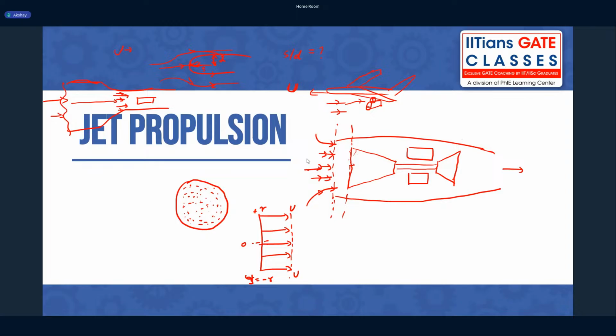Okay, so the increase in pressure and the deceleration of the flow, they are not the primary purpose. Of course, we are doing it, but they are not the primary purpose. The primary purpose is to make sure the compressor sees a nice, uniform, undisturbed flow. Everybody clear?